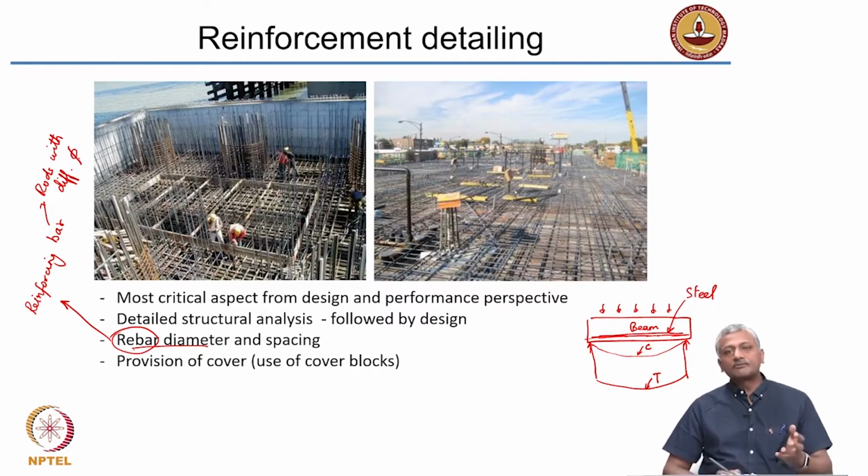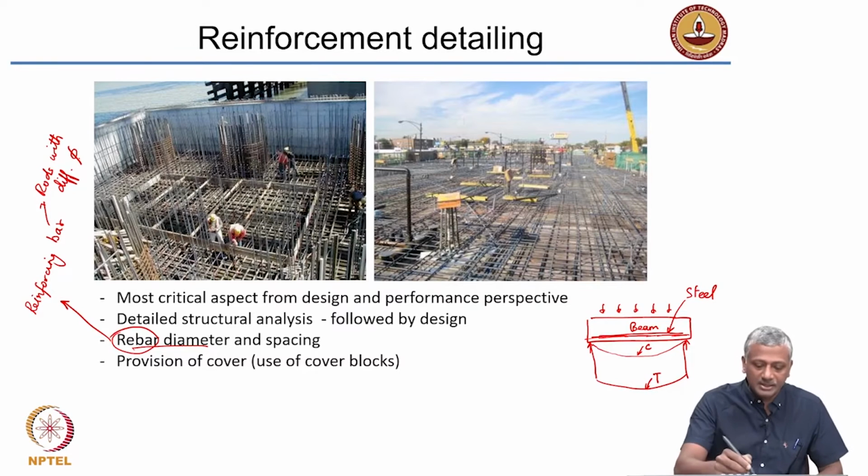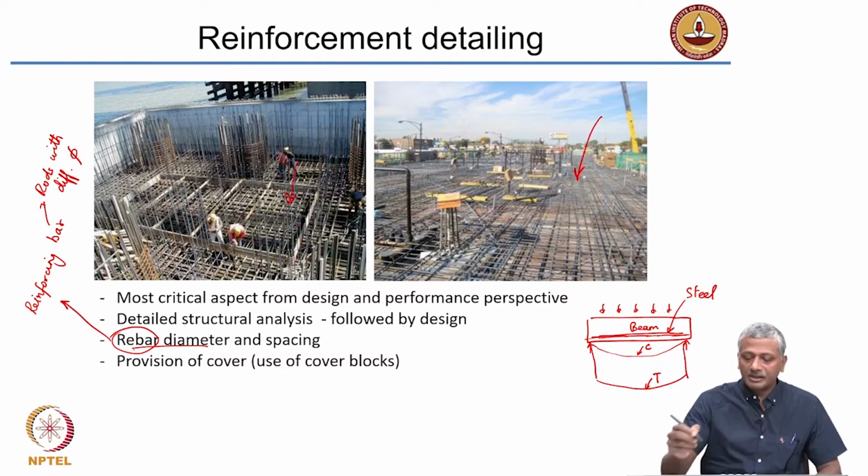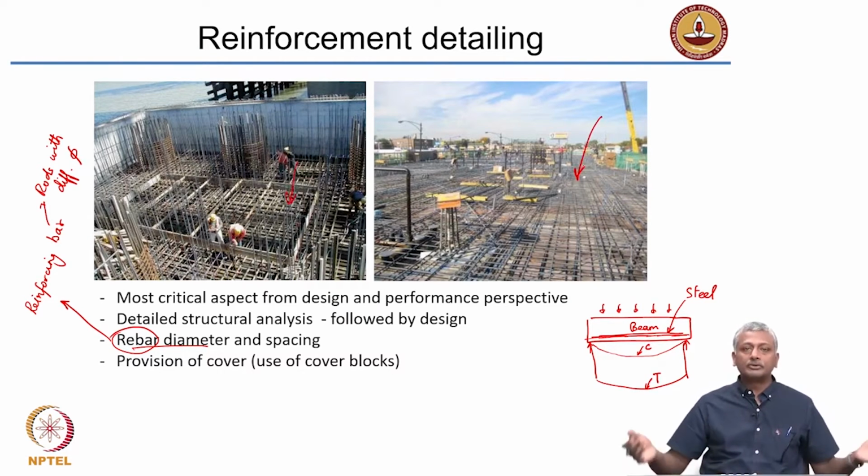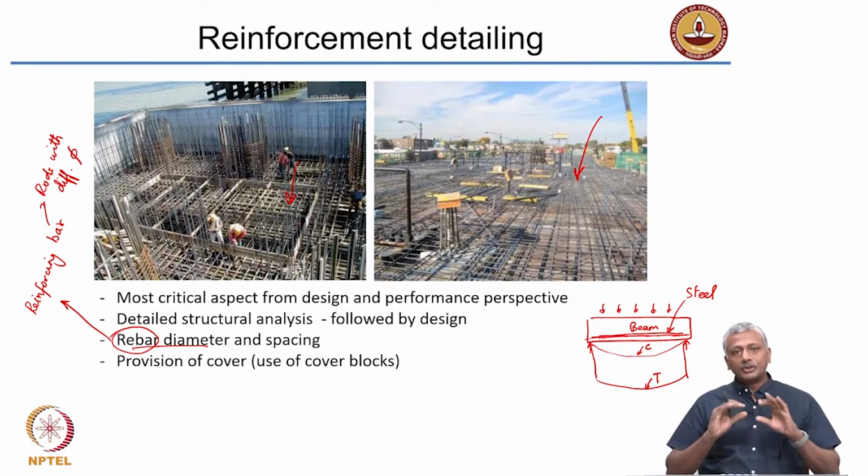All this, of course, you will learn in more detail when you actually encounter courses on reinforced concrete design. But it's very important to understand that before the concrete placement into the formwork is done, the reinforcement has to be appropriately designed and laid out, like you see in these pictures here. The reinforcement is properly laid out before the concrete is poured to ensure that you are getting reinforcement in all the zones which are going to be experiencing tension.